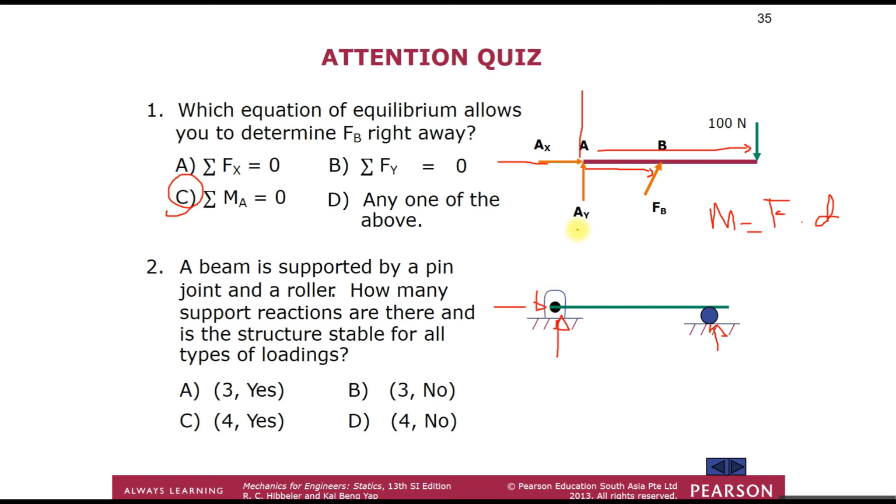So is it stable? Also, how many support reactions? We have three: one, two, and three support reactions. And is it a stable structure for all types of loadings? No, it depends. If the loading does not require rotational movement, then it will be good.